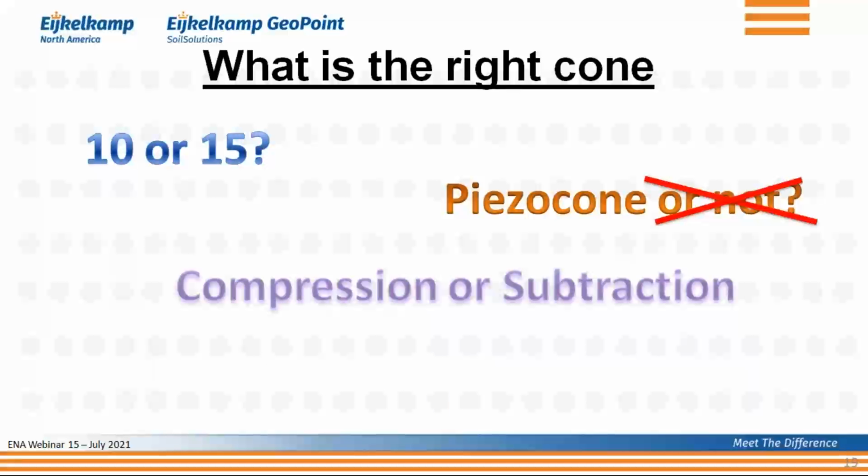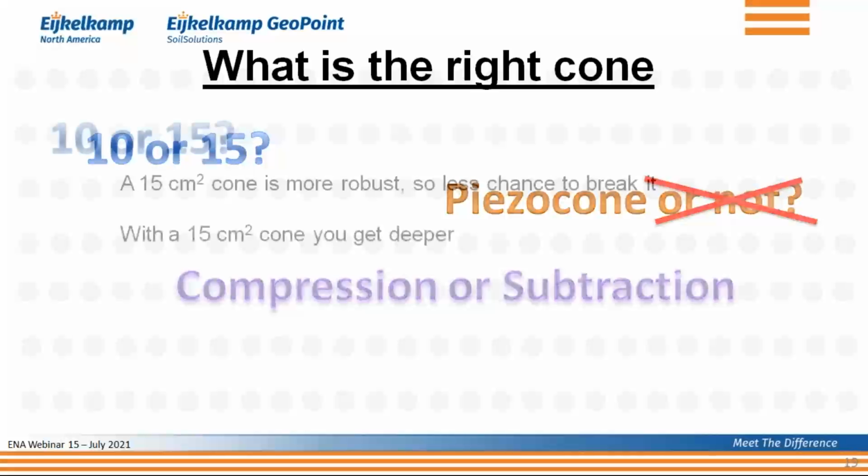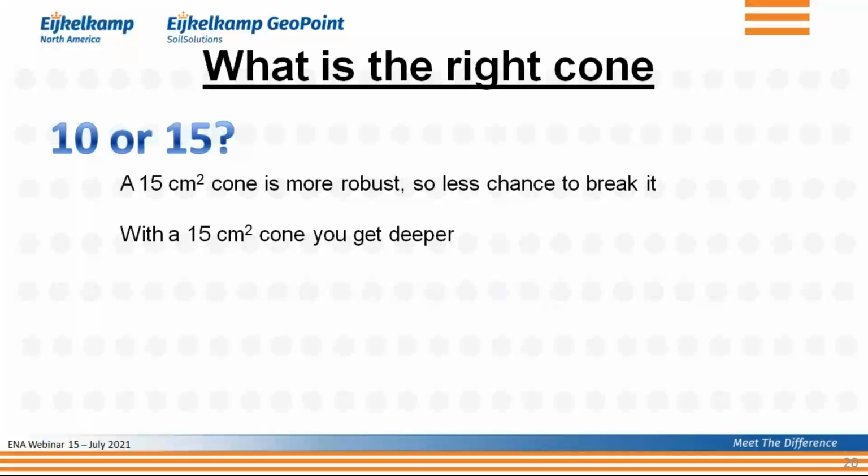The 3 questions that I have. The first one is really simple to answer. Piezo cone or not? No, use a piezo cone. More information, accurate information, and it allows you to correct your data point. So that's simple. Let's then go to the second one, 10 or 15.